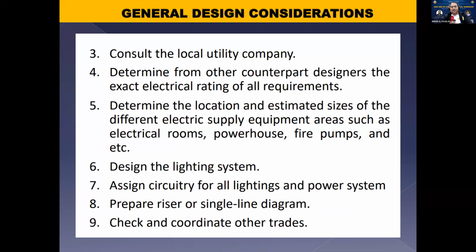Then design the lighting system. You can also evaluate it as per illumination level requirement, so you can determine how many lights are required for a certain area. Then do the circuiting of the lighting and power system. Then the single line diagram and coordinate with other trades.